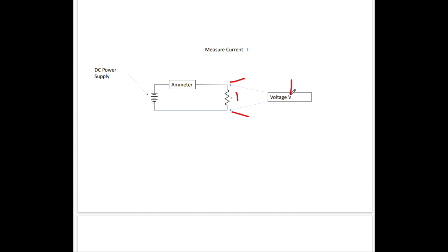And I'm never going to change that voltage. So I'm going to do 3 different experiments. I'm not going to change the voltage. And I'm going to hook an ammeter up in series, and we're going to measure the current. Okay, this is step 1. Whatever the current is, it is. This resistor is going to choose that current. We're going to figure out what that current is.